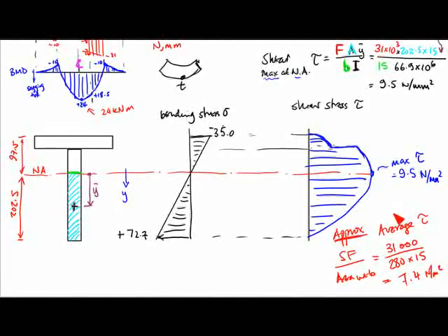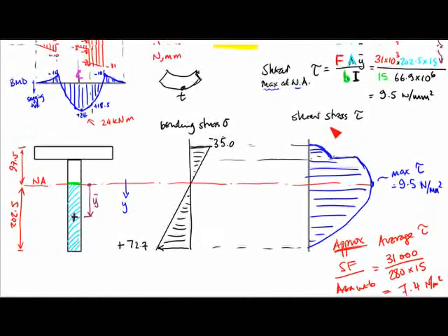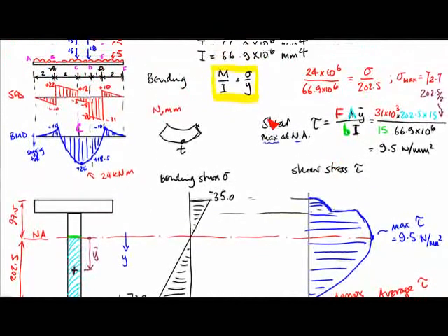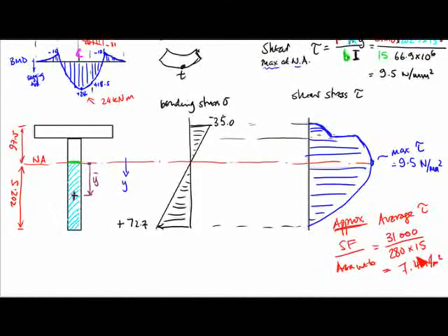And so for practical work, we fairly often just go for what we call the average shear, because that's not going to be very different to the maximum, and if we have a beam where the depth is quite small, and the beam is quite long, and the normal loading, this is a good enough figure to work by.